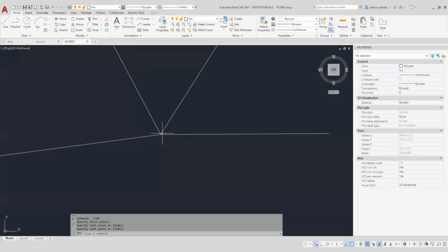You might find you're in a congested area and you need to select an object. If we hold Shift, we just hover over these. One of these is highlighted. If I hold Shift and press space, it will cycle through each of the objects on that common point or within a tolerance. So I've got the one to the right highlighted.